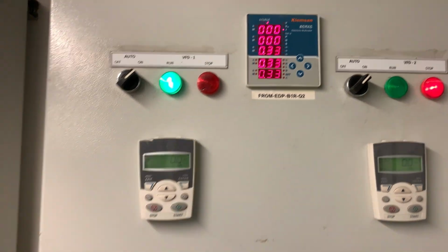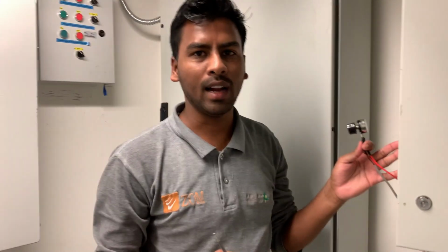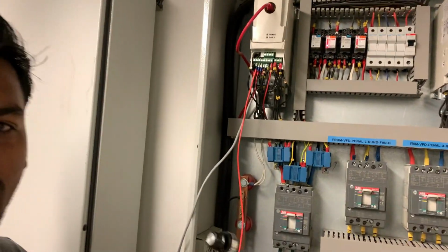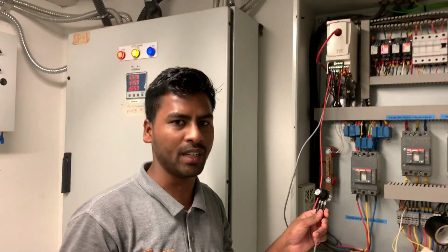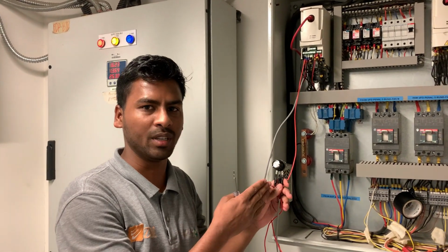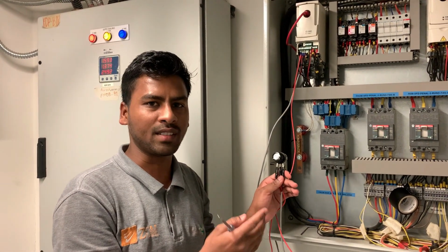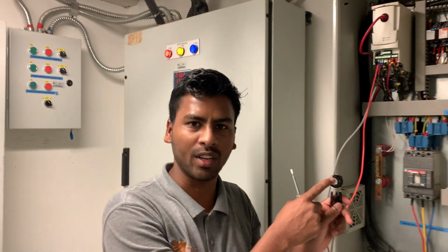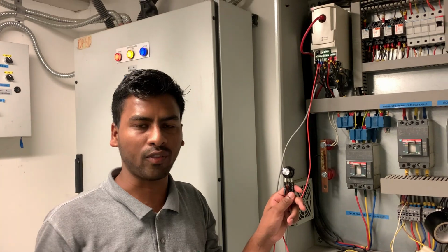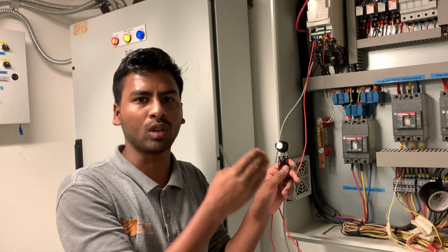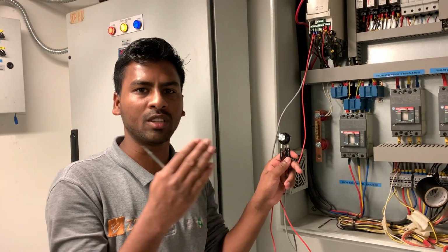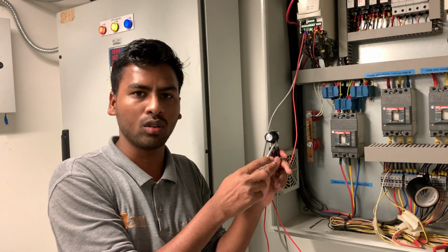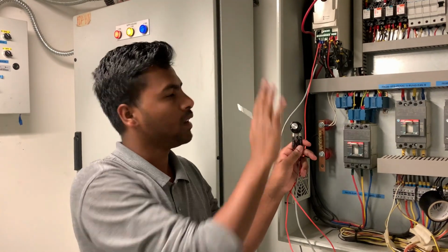In this video tutorial I'll show you how we can run the VFD ACS drive, and how we can increase or decrease the speed either from the BMS or from the potentiometer. This concept is the same. We are increasing or decreasing the speed voltage from the potentiometer. But if you connect it from the BMS, you have to give the command from the BMS. If you press 50% in the BMS, it will trigger the DDC and the DDC will supply 5 volt to this analog input pin 1.